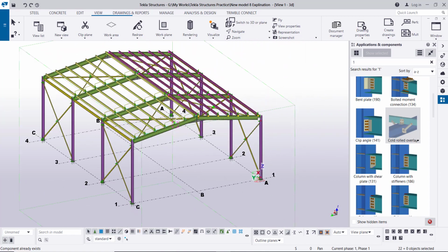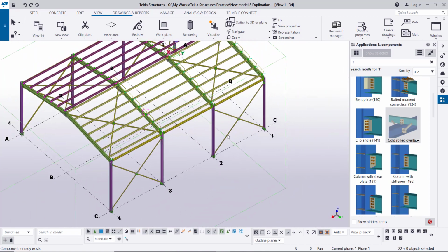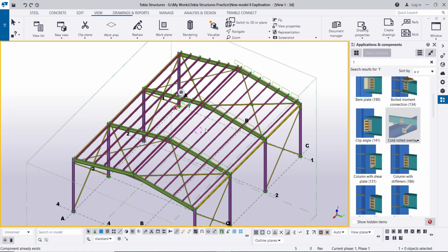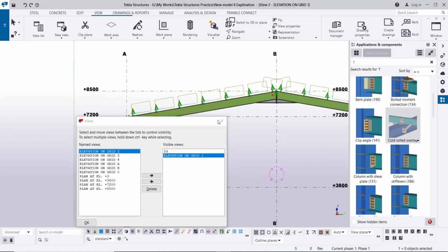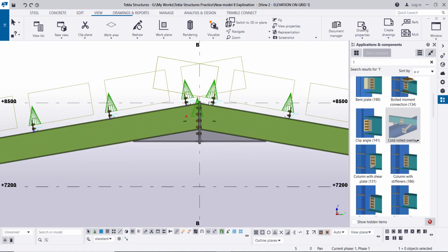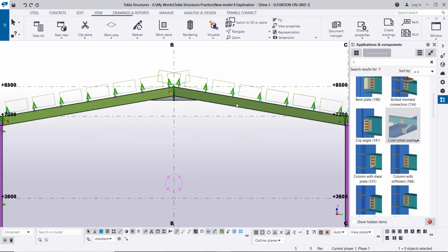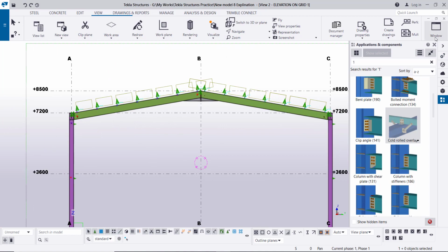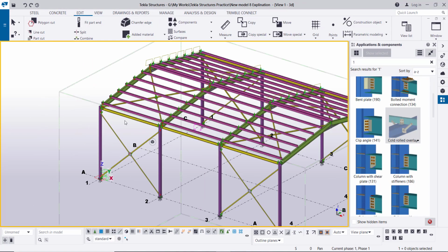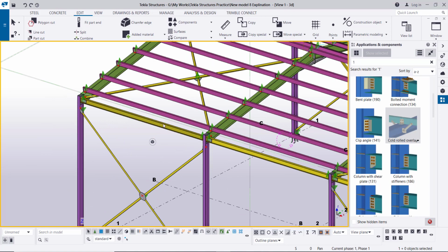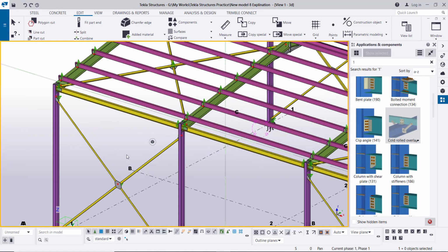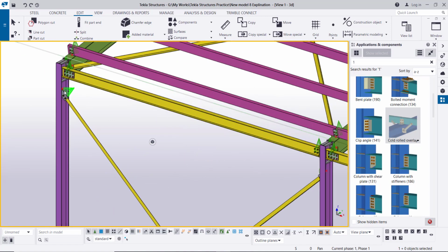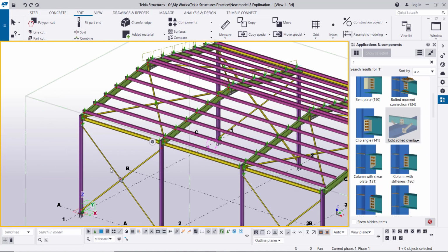Okay, so like this, we see our purlin already mirrored. And if we go to any grid, like grid 1, we can see our purlin with the proper connection already created. Okay, now we need to copy these beams, strut beams at the mid-level, because the column is 7 meters, so we need an intermediate beam. First, I will shift this cross bracing a little bit